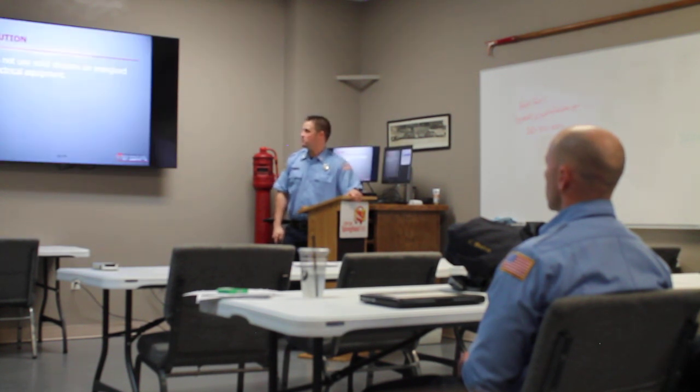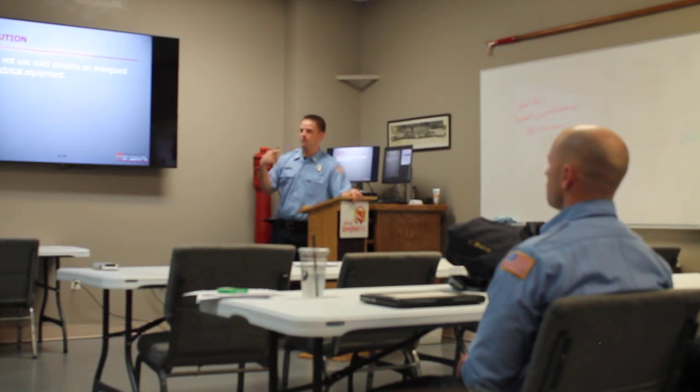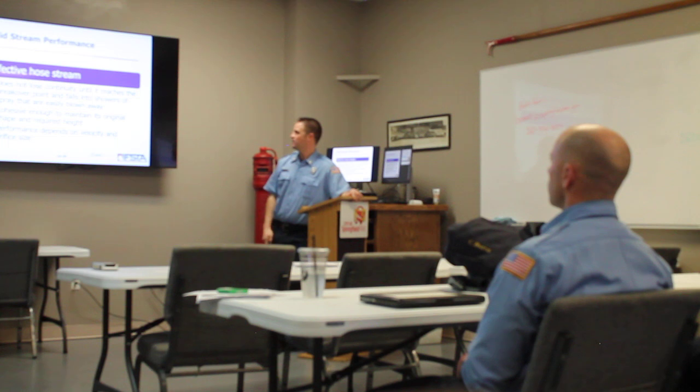Do not use solid streams on energized electrical equipment. I guess a telephone pole on fire, or a big breaker box in one of those industrial places that's burning, you probably don't want to do that. It's going to conduct faster than the fog nozzle would, since all those water droplets aren't stuck together as much.